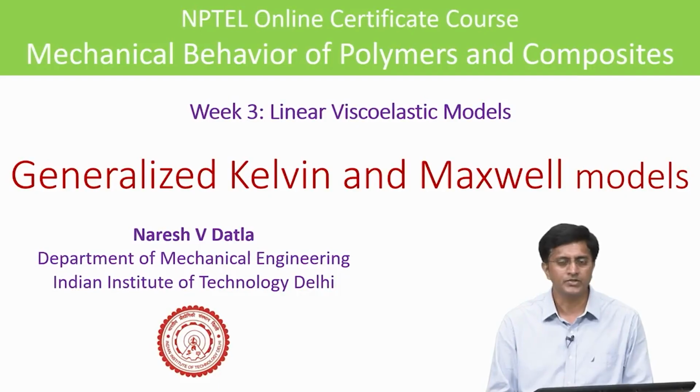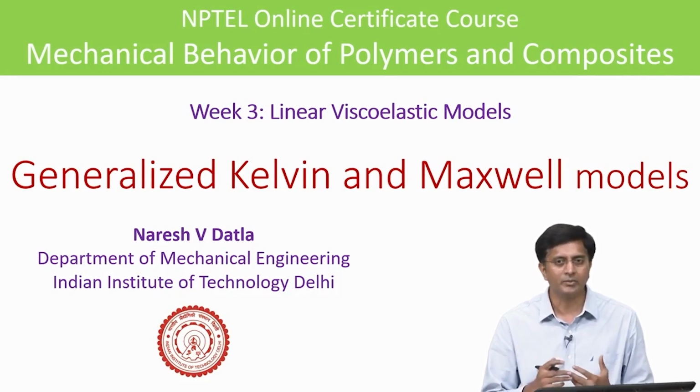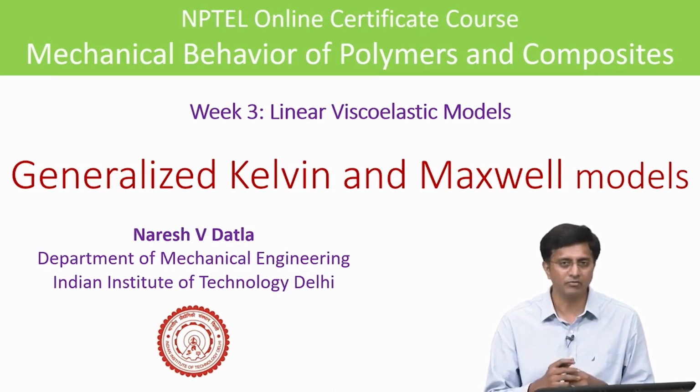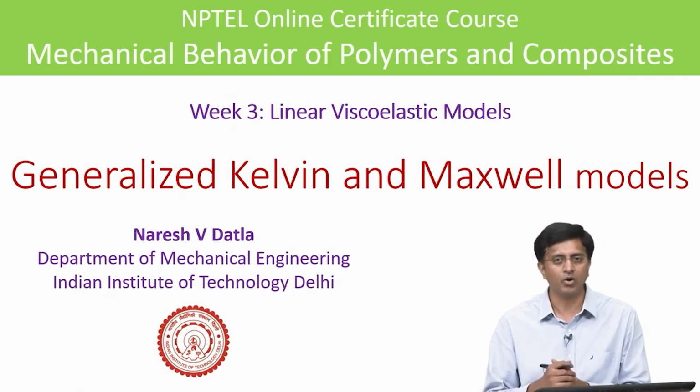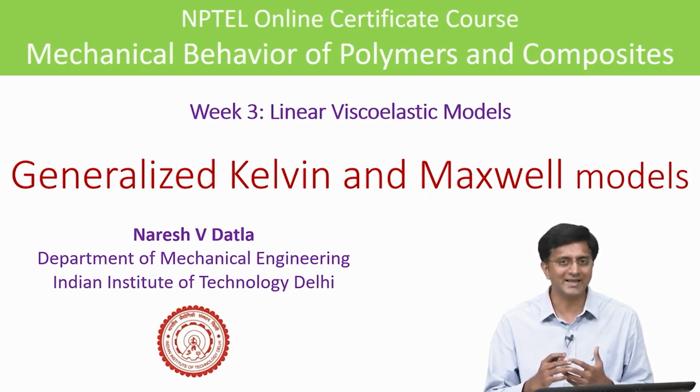Hello. In this video, we will be looking at the generalized Maxwell and Kelvin models. We need to recall that the Kelvin and Maxwell models we discussed are now the building blocks for us to develop these generalized Maxwell and Kelvin models, because these can be used to model a real polymer. A real polymer has several relaxation times or retardation times which cannot be captured by a simple one Maxwell model or a one Kelvin model.